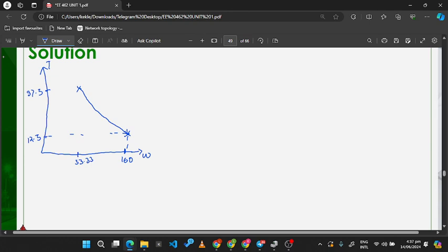Then the next is to calculate the rating of the motor. The rating will be given by the torque times the speed. But in the first scenario, we are assuming field weakening is not possible. So the motor has to be able to supply this maximum torque at all speeds, and continue supplying it even at this speed.